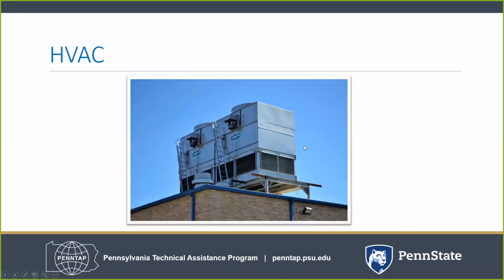Building envelope. In building envelope, install weather stripping, caulking, insulation around windows, doors, and penetrations. Implement a formal energy policy for your facility. Reinforce appropriate use of drapes to improve comfort. Locate occupants away from problem areas. Use controls to automate functions. Apply low-E film on windows. These are just a few measures.